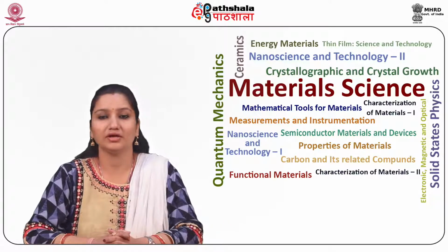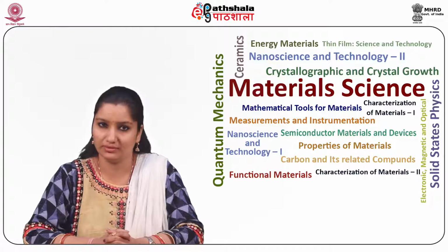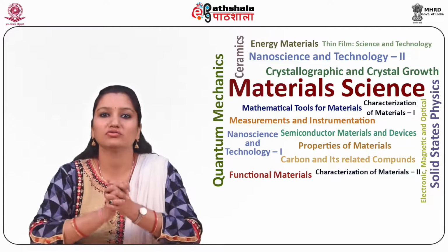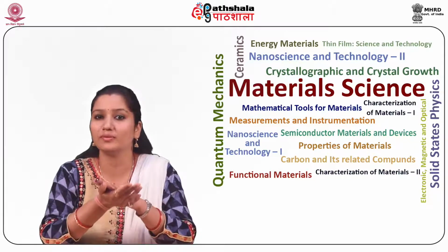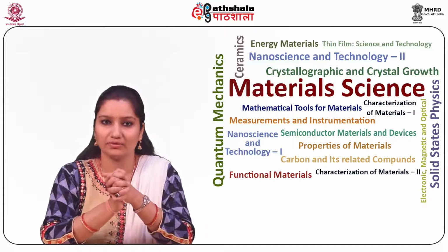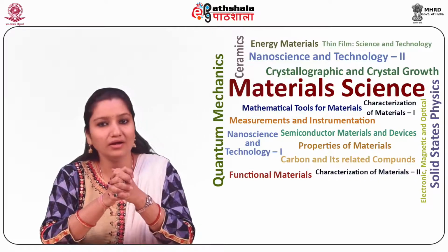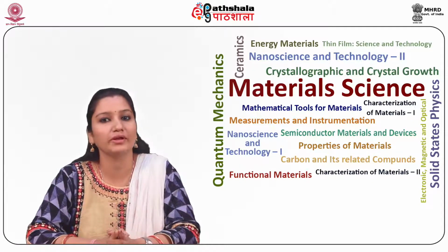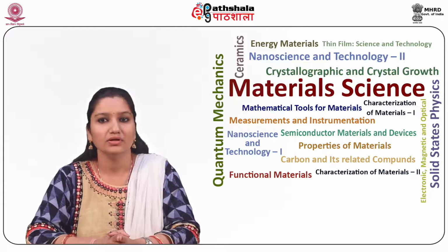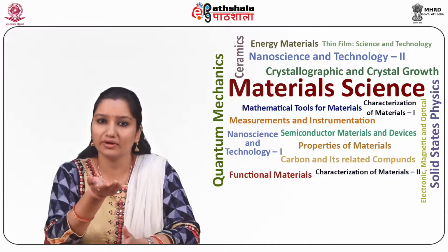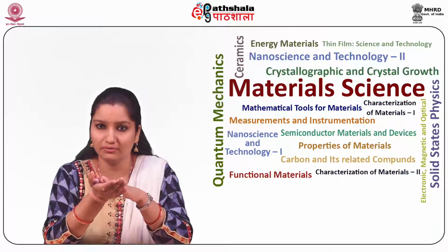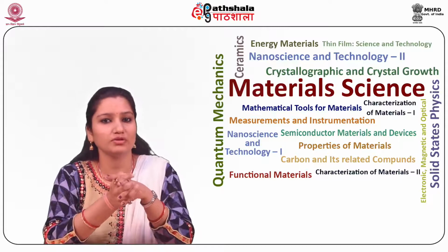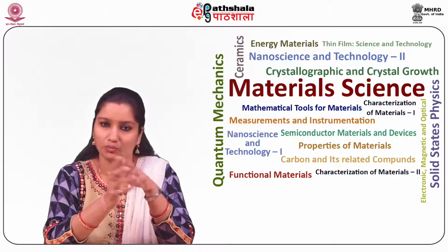The next technique that we are going to study is spin coating. Preparation of a highly cross-linked solid thin film onto the substrate can be achieved by means of hydrolysis and condensation of the molecular precursor using the spin coating technique. In the spin coating technique, the substrate is placed on the chuck table and held by a vacuum of the order of 10 raised to the power minus 2 millitorr while rotating.